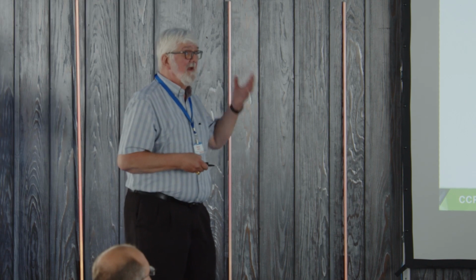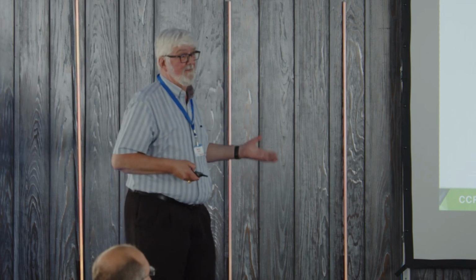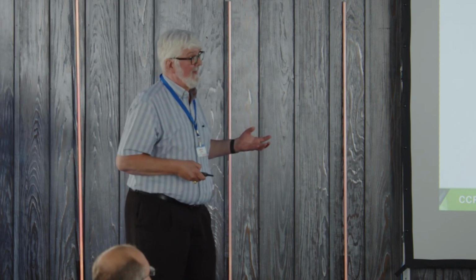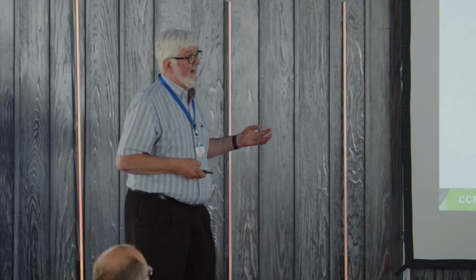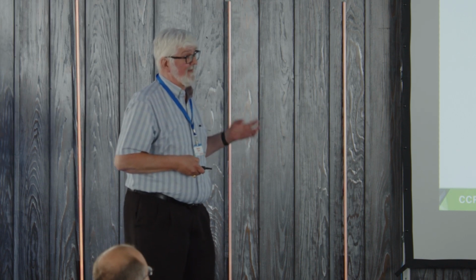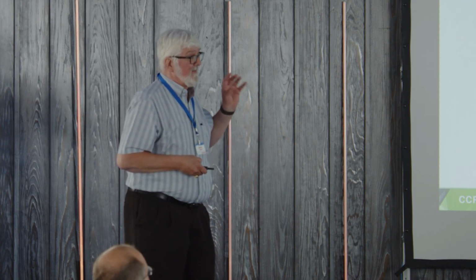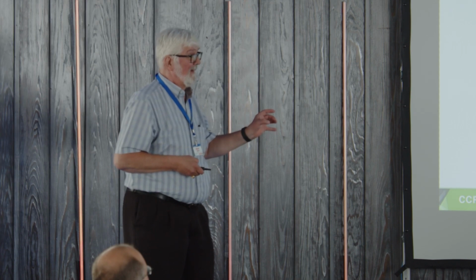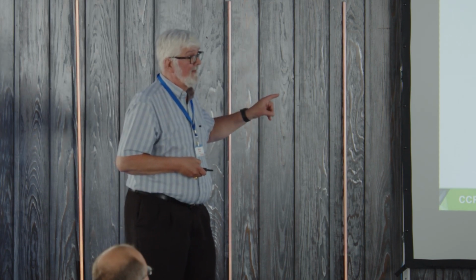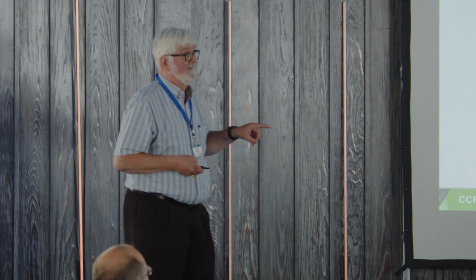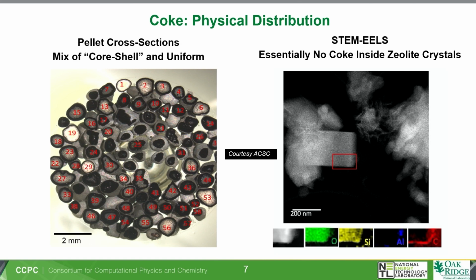Why does that happen? In my mind, I'm a catalyst guy for decades. It's very simple. I've got too much ZSM5. I don't have enough mesoporosity. I don't have enough matrix. It's decomposing very quickly, and the heavier molecules are not even seeing the core. And that needs to be taken into account when you do the kinetics extraction.